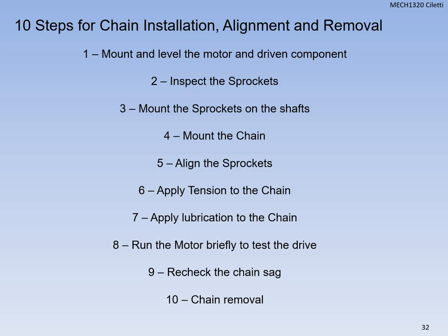You're going to inspect the sprockets, mount them, then you're going to mount the chain. Okay, align the chain sprockets, apply the proper tension, lubricate the chain, run the motor. All right, and then you're going to recheck the chain sag and chain motor. Okay, those are just general steps for install. You guys are going to do one of these labs in person. All right, on the trainer.